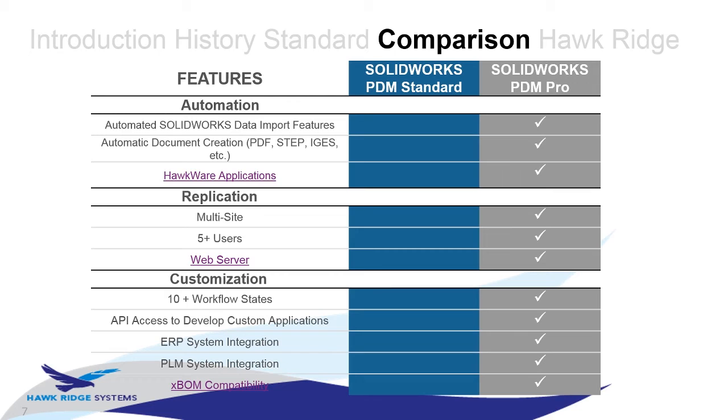The second caveat to know about is those local database servers are only there for read access. So it's good in terms of searching and finding files and just having read access to your vault for performance. When it comes to actually writing metadata, such as checking a file back in with new custom properties, that will still communicate with the main server. Okay, so just for those of you who might be interested in that, just so you're aware of it.